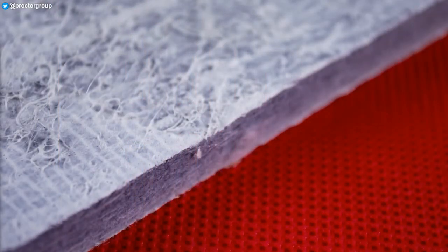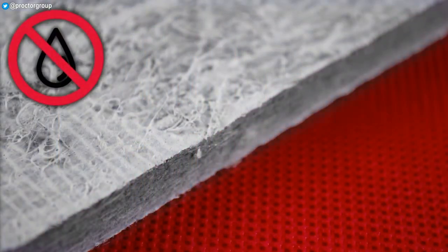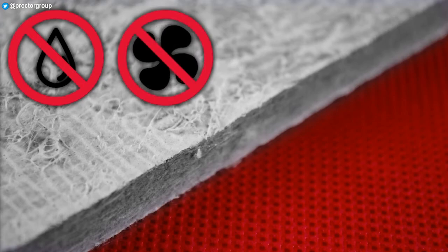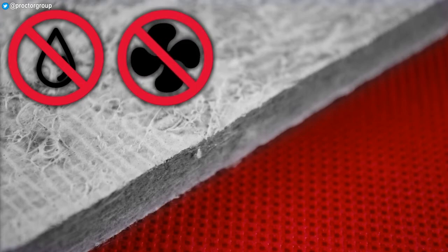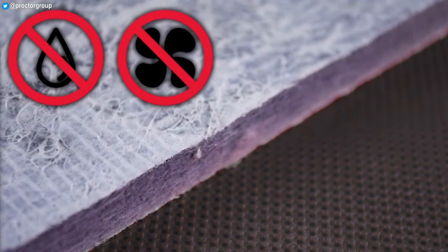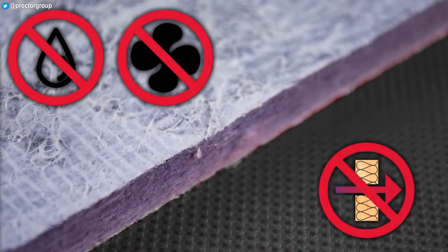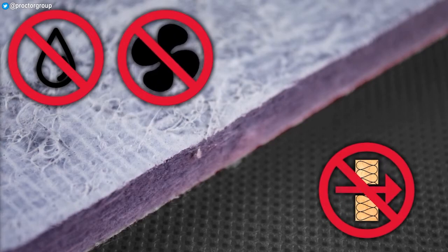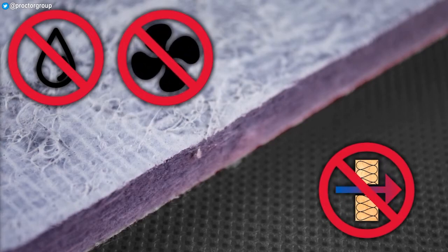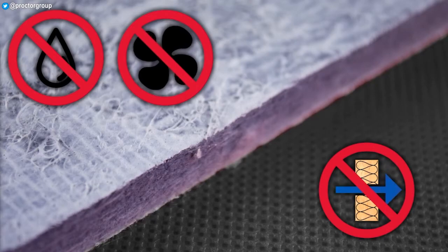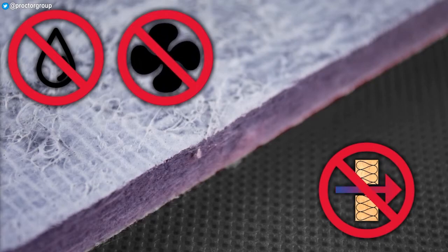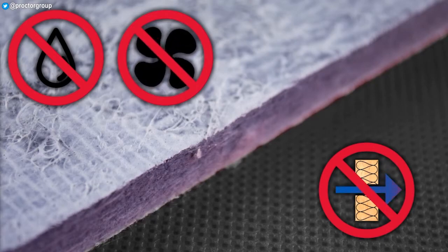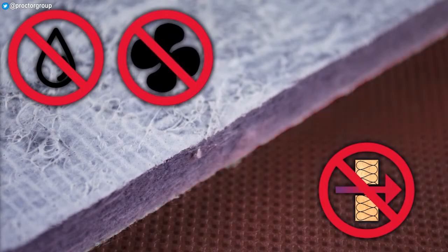As well as protecting the existing building fabric, Wraptherm's hydrophobic properties provide a secondary barrier to water ingress, and by sealing tightly to door and window frames and other penetrations, also limits heat loss associated with air leakage. The unique layer of aerogel insulation in the Wraptherm also effectively limits cold bridging by providing a continuous insulation layer across the back of the facade, so there's a thermal break between the new structure internally and the cold outer stonework, providing a further boost to the energy performance of the upgraded building.